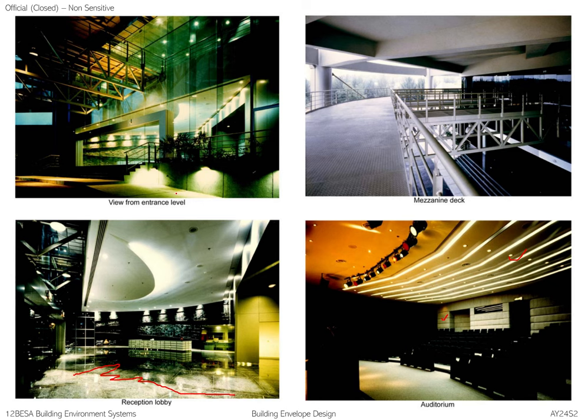Okay, the reception lobby you see at the bottom, you notice that it uses a very reflective surface for the floor. This is one of the techniques that you can use: using reflective surfaces to bounce diffuse daylight deeper into the space. But you have to be careful, because we don't want it to be so reflective that it compromises the privacy of the user of the space. But that is one of the common tactics that we use. Alternatively, you can use it on the walls, so let the wall do the bouncing off. But be mindful, as mentioned, about modesty, and be mindful about glare also.